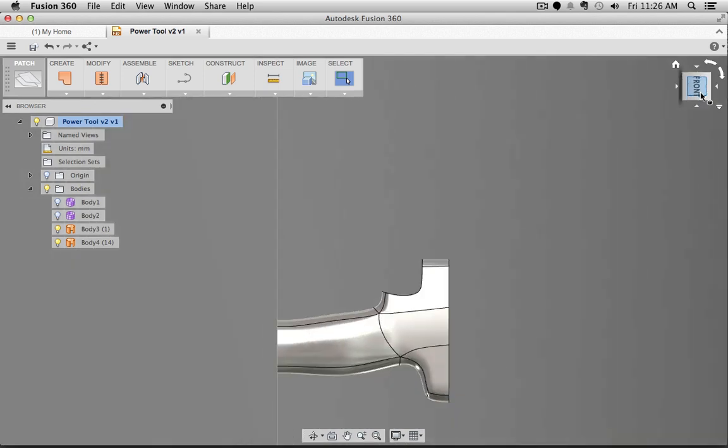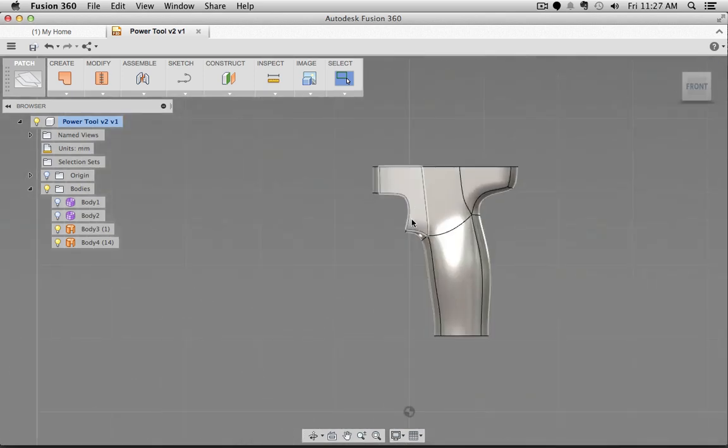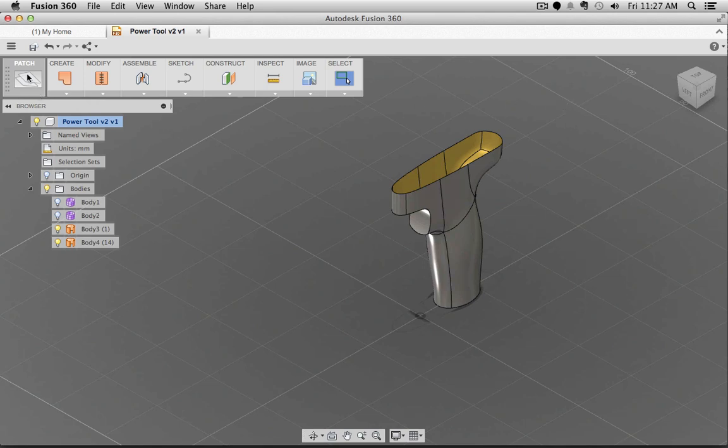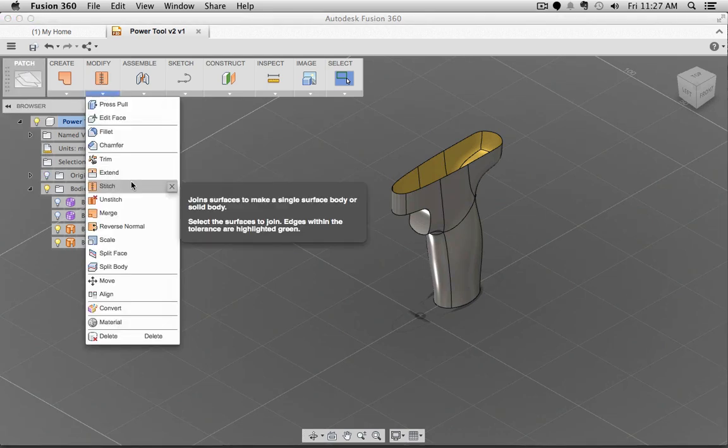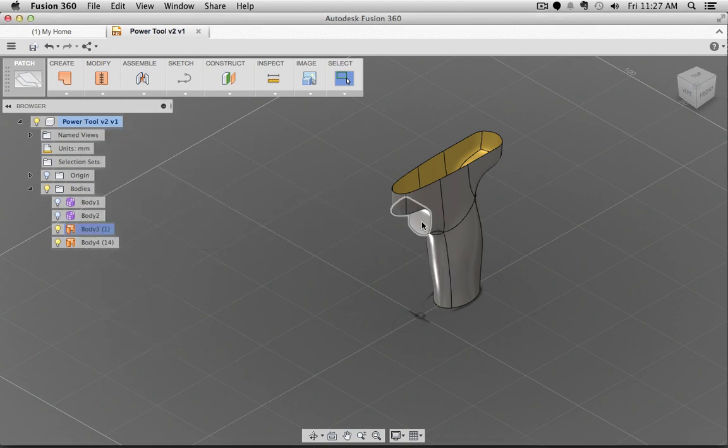And let me introduce to you, for example, now one of the key features besides this trimming, what you can do with NURBS and solids, what you can't really do with polygonal models. So I have here a command called stitch, and stitch basically means it is sewing the different surfaces together. So for example, here I have one surface, and then I can select those. So you see there are different surface patches, and they all basically share kind of like those edges and then flow nicely together.